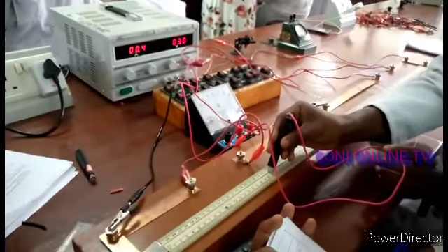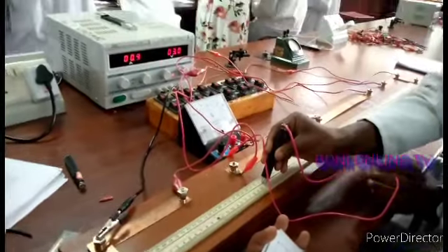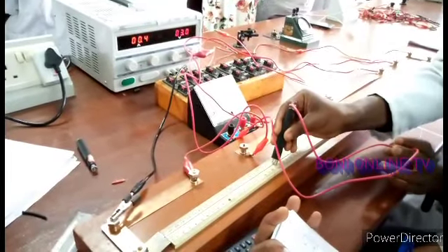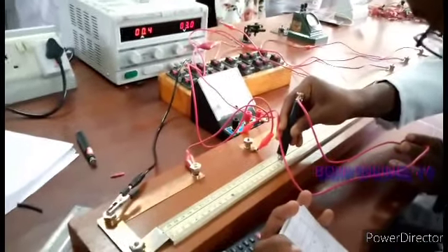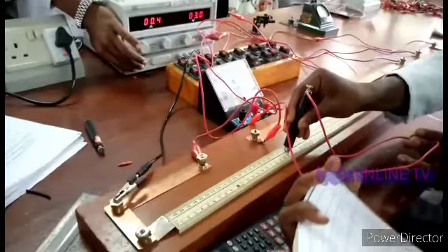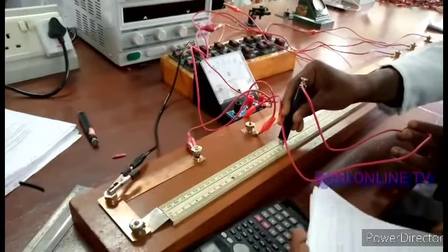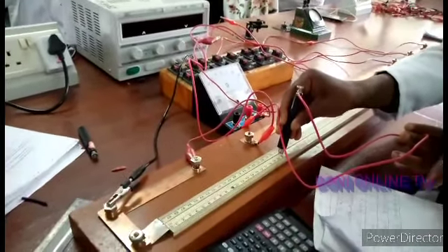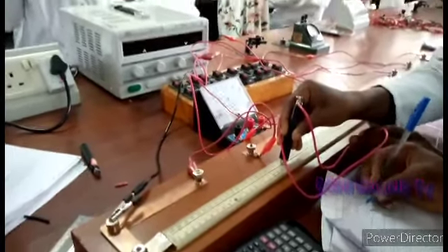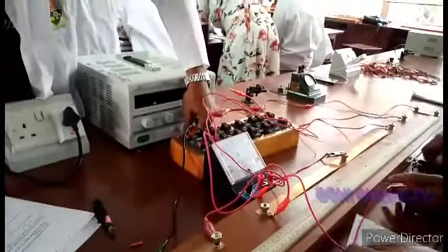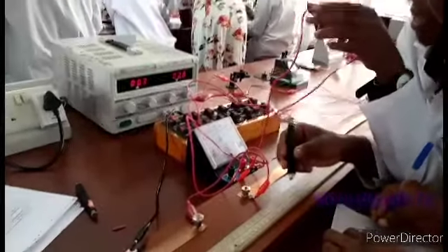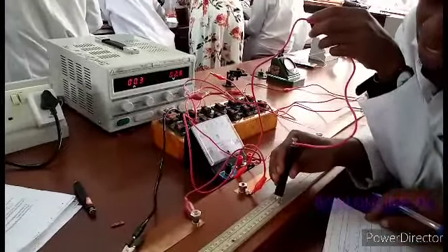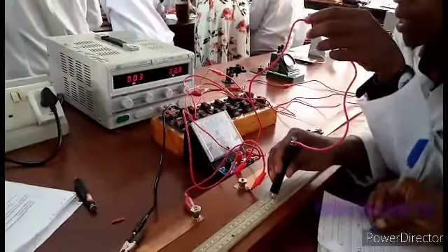So the power supply is normal. As you can see, I have changed the resistance using another unknown resistance. Here resistance 1 and resistance 2 are connected normally, and the power supply is also connected in forward bias. What has been changed, remember, is the unknown resistance. Then I have to reverse the connection of the power supply with the circuit, negative to positive and positive to negative. Then I also find the balancing point.